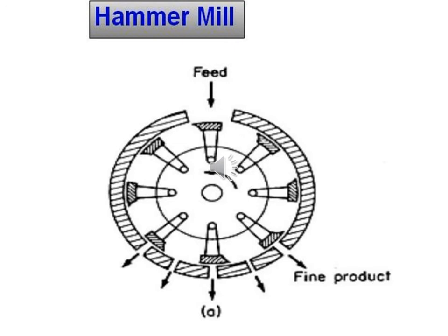This is the schematic diagram of the hammer mill. The hammer consists of different types of devices through which the material will rotate at high speed and be struck or impacted by these devices, then transformed into fine particles, which can pass or discharge through the screens.